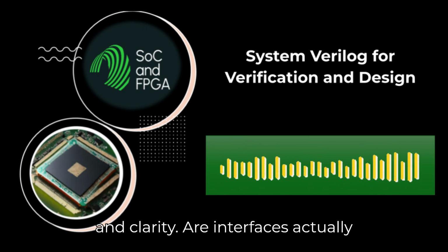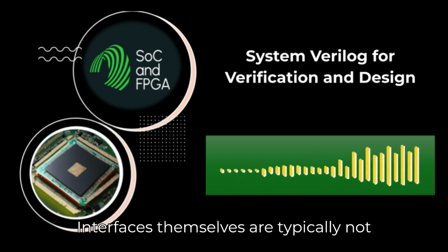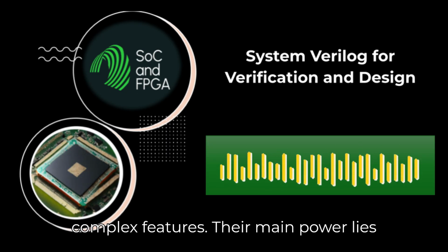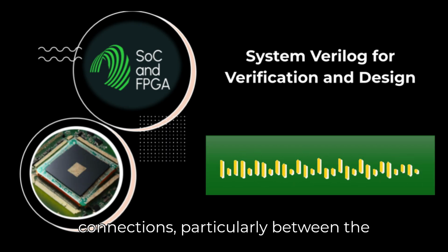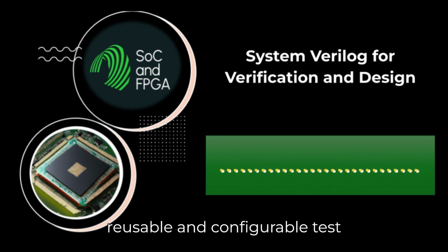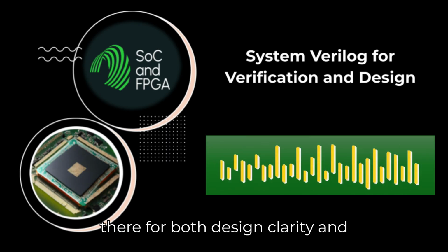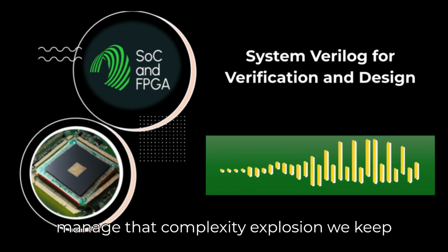Are interfaces actually synthesized into hardware? Generally, no. Interfaces themselves are typically not synthesizable, especially the more complex features. Their main power lies in abstraction and simplifying connections, particularly between the design, the DUT, and the verification testbench. They are fantastic for building reusable and configurable test environments. Okay, so abstraction is key there for both design clarity and verification setup. It really helps manage that complexity explosion we keep talking about.